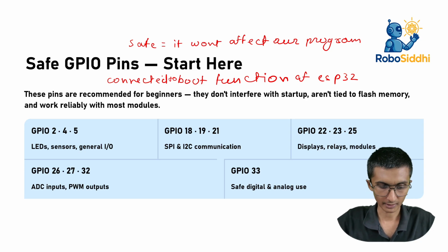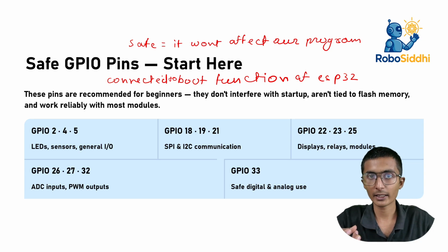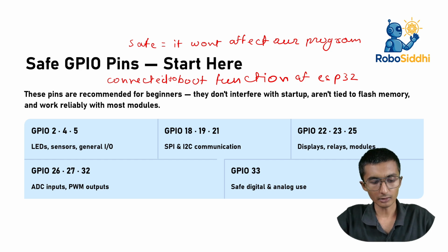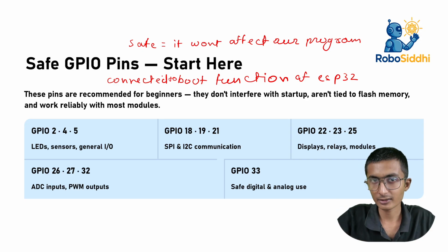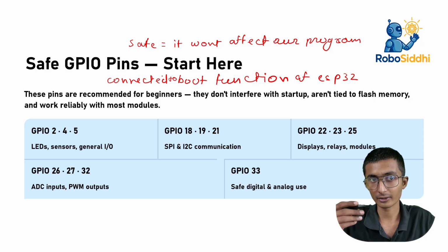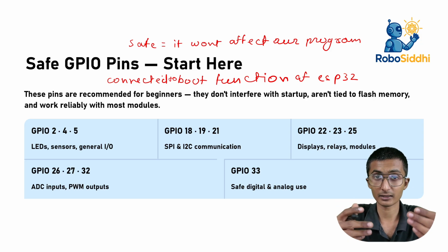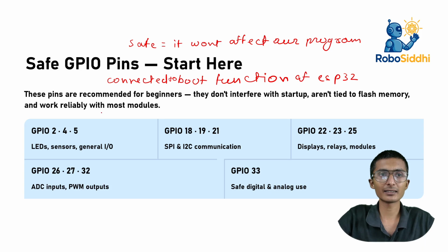So you have a basic idea of what is a boot. Boot is basically starting some electrical equipment or any kind of computer. In ESP32 it's also a computer sort of. So whenever you are going to use those pins, you have to remember that if you use them, your ESP32 can crash the program and reboot again. So be really careful with that.